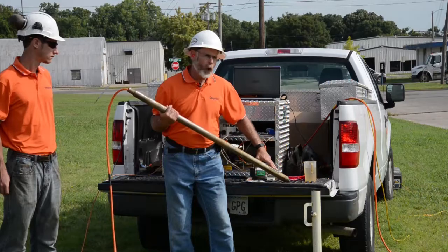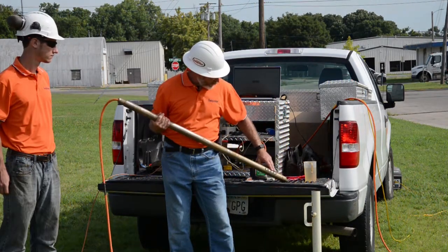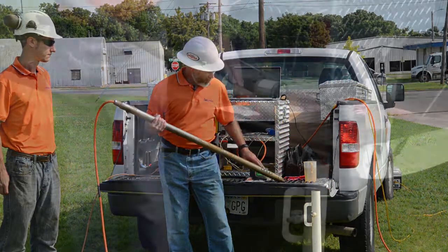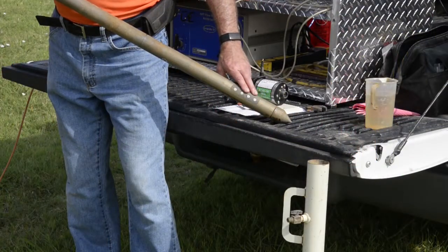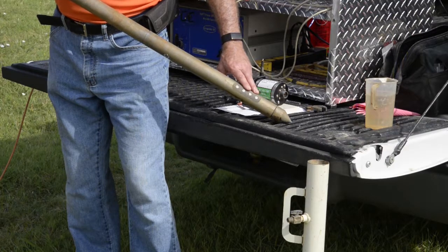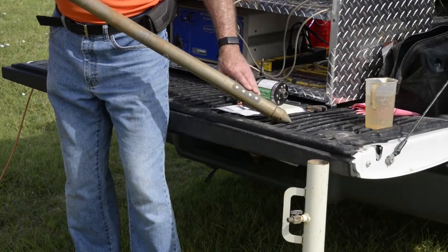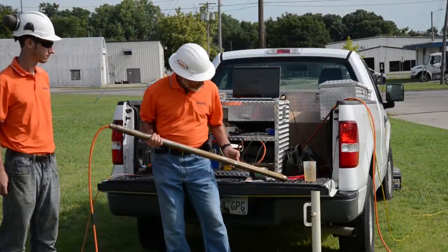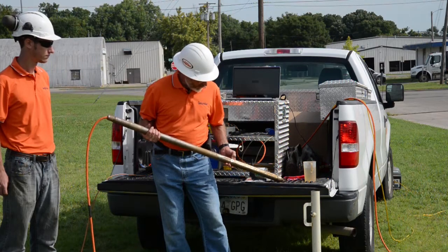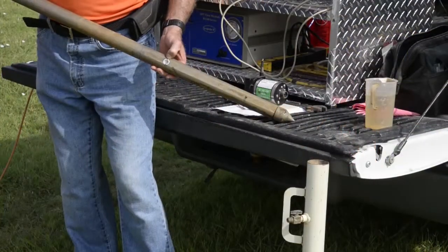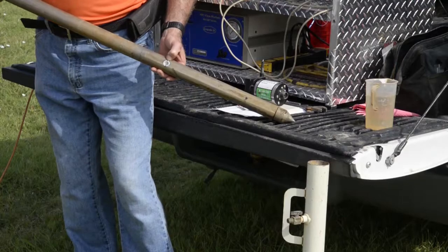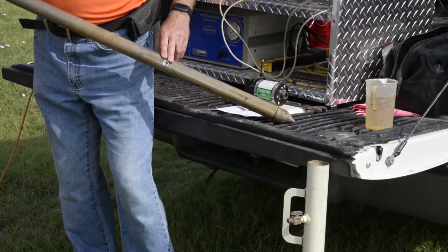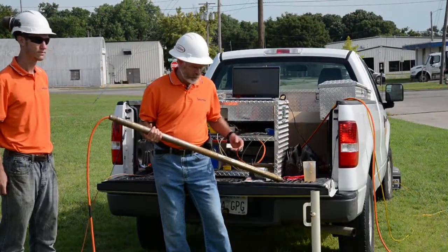On the lower end of the probe, we have 4 electrodes that are isolated by an engineering plastic. This is our electrical conductivity array. It is a Wenner array, so we get an electric log from this. Further up on the probe, we have our HPT screen. This is a wire mesh screen, and it's replaceable, so if the screen gets damaged in the field, you can take it out and replace it.